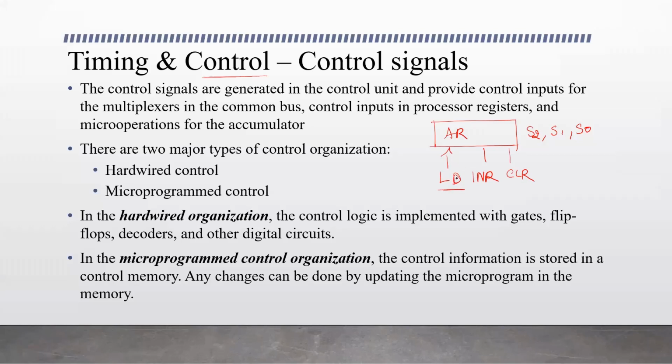When this particular control input is enabled, and at the same time the clock pulse goes high, the operation will be performed. So any operation is controlled by the timing of the clock: when the clock edge goes high, the positive edge of the clock activates it, at the same time when the control input is enabled.